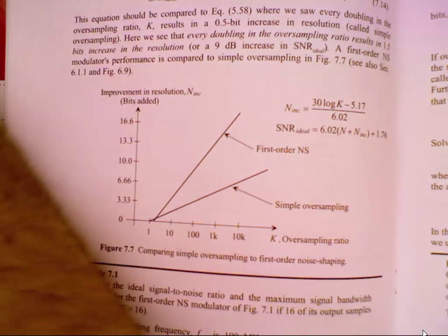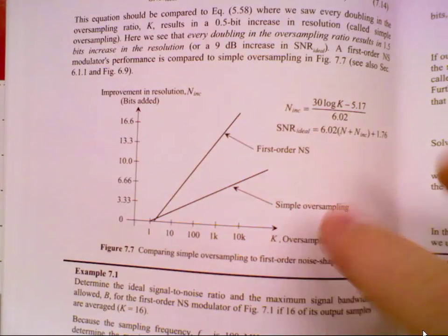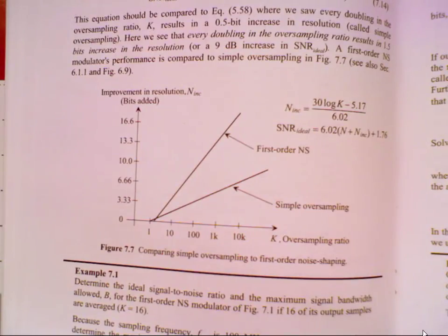Maybe someday you'll see that come into play again, but it's very simple to implement because your bit line is a big capacitor, and your memory cell is a current being pulled out, so your delta sigma is just like a D flip-flop in a feedback path to keep the bit line at a constant potential, or to add the water back in. So if you average 10,000 points and your feedback current is like a microamp, now you're at like 10 or 100 nanoamps, and you can even sense longer because the sense can be indefinite, so you can really shoot up the signal to noise ratio, and average out noise and mistakes and all that.